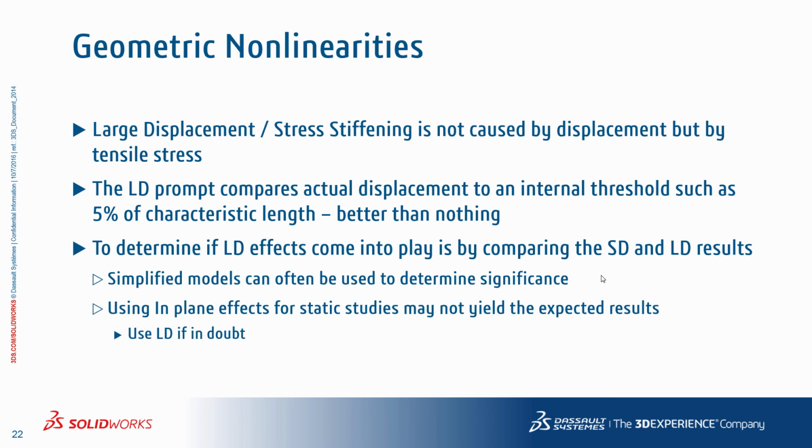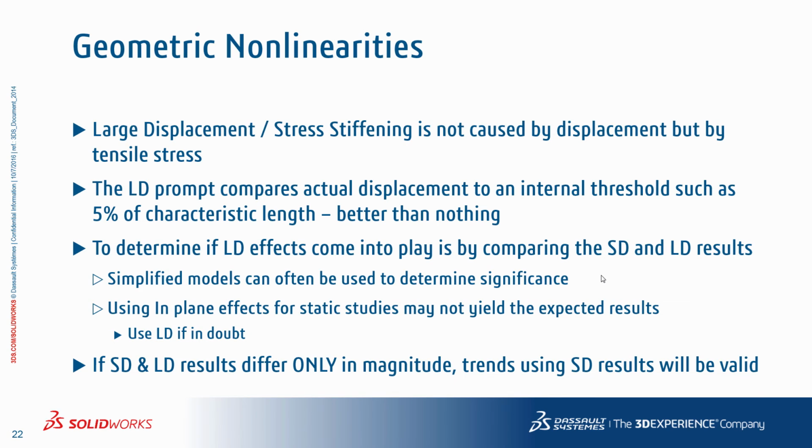Now, to truly determine if large displacement effects come into play, compare the small displacement and the large displacement results. So you can use simplified models to determine the significance, and using in-plane effects for static studies may not yield the expected results. So always use large displacement if in doubt. And finally, if small displacement and large displacement results differ only in magnitude, trends using small displacement results will still be valid.